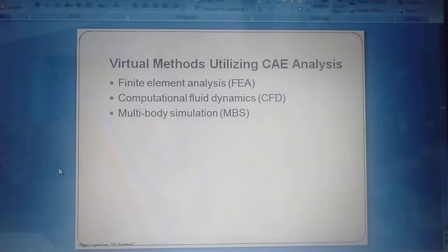The data transfer from the 3D CAD model into the CFD program is performed by neutral standard data formats, for example STEP and IGES formats. The boundary conditions for the calculation are defined directly in the CFD program. Solvers like CFX, Fluent, Nastran, etc. are a few software used to conduct this type of analysis. You can use it for liquid and gas flow, heating and cooling, and chemical reaction. This is not possible in an FE analysis.